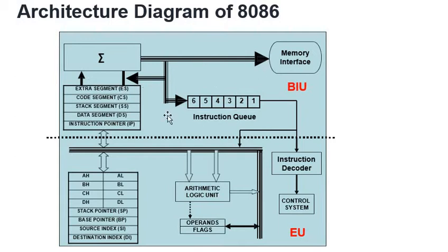So for this 8086 microprocessor, since it has 16-bit data, it can access 16-bit data. Whatever data is to be taken or placed on the memory will be accessed with the 20-bit address. So 20-bit address lines are available with this 8086 microprocessor. Based on the 2 power 20 calculation, that is 1048576, 1 megabyte of memory can be interfaced with this 8086 microprocessor.